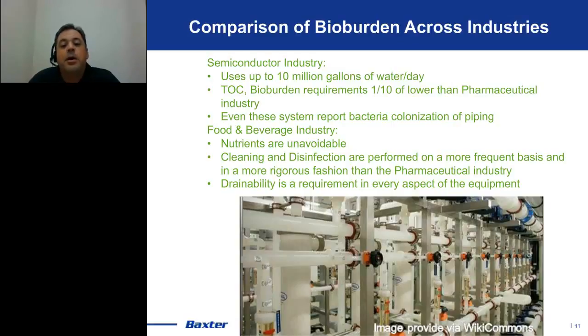Examples such as peanut butter, which getting off of a surface is certainly got to be some work for that industry, is certainly doable. And one of the ways that we'll talk a little bit more about is not only having good cleaning and disinfection, but also making sure their systems are as dry as possible. So worrying about things like drainability, not using water when they don't need to, things along those lines.